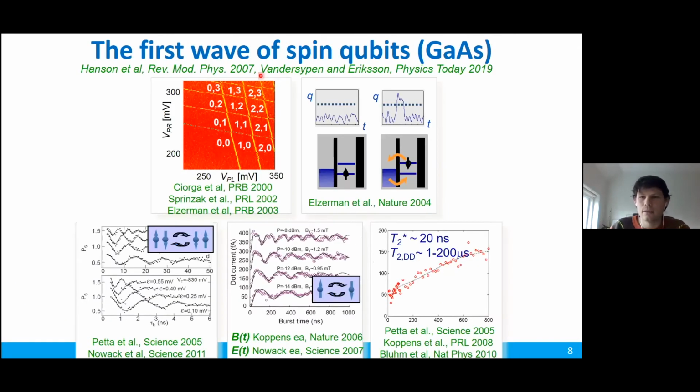Well, the effort with gate-defined quantum dots has, for the last two decades, mainly been led by experiments on gallium arsenide as a material. And this has enabled various results to be achieved. For example, the well-controlled number of electrons, indicated with this so-called charge stability measurement, where gate voltages are varied. The electron occupation can be understood from the different transitions in the diagram and can be controlled up to the number where the dots only have a single electron each or are even fully emptied.